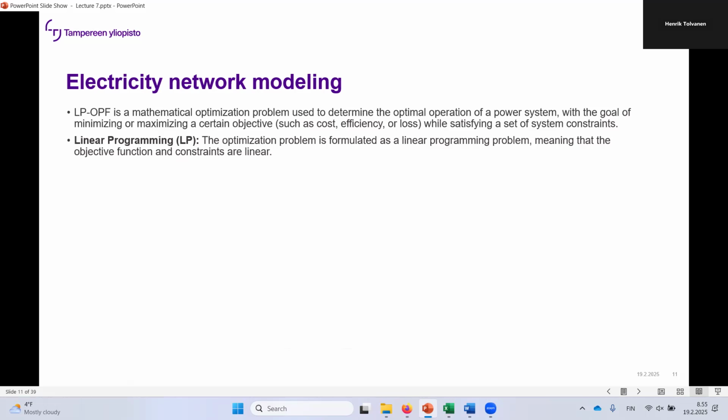So you want the energy security in a way that you don't overshoot the production in a certain area, and then the transmission line capacity is being exceeded. So you have to have this energy security, but also you are aiming for this economic dispatch. So the economic dispatch means that you have the lowest marginal cost for the system to operate.